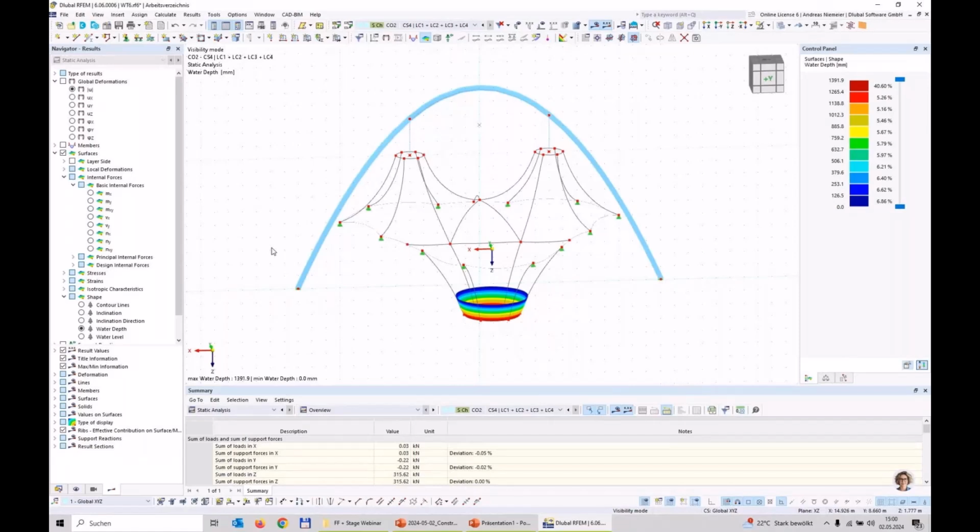And because we want to make it really efficient for you, we programmed it with some automatism now. So in future, you can define some master cutting lines on the mesh and define a width of the material roll you expect or you can manufacture, and the program is detecting for you automatically the remaining cuts to reach a specific width of a roll of material. And let's say this is at the moment our biggest job in this field, and we try to finish it soon. And now I hope you enjoyed this webinar, and I give back to Jürgen.